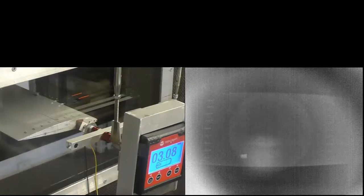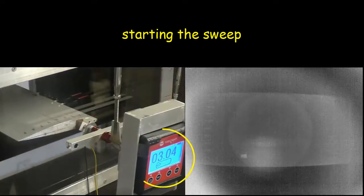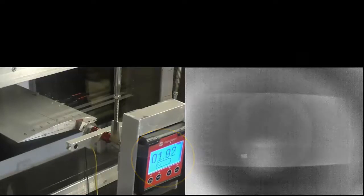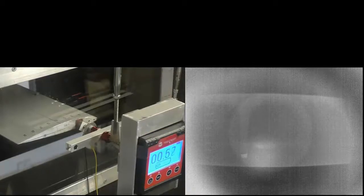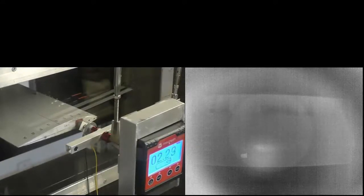Because of this, one prefers to first set a single angle of attack, wait a short time for flow stabilization, and then record the infrared image. Waiting for flow stabilization ensures that the infrared image fits to the actual flow state. If the infrared image is taken, the next angle of attack is set and the procedure repeats. Normally, other measurements are done in parallel to the infrared measurements, and if one combines these with, say, lift and drag or a pressure distribution, one can get valuable data about a profile, wing, or a complete aircraft.